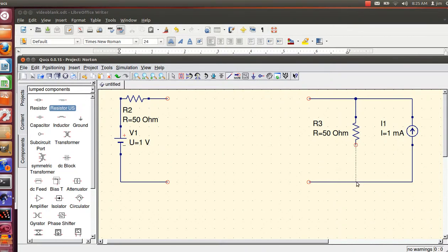Okay. So the end of the day, as a friend of mine used to say, if you do a Thevenin, you come up with a voltage source with a series resistance. You do a Norton analysis at the end of the day, you'll come up with a current source with a parallel resistance. If I was to put a black box over both of those, I could set the values up so that they would have the same characteristics. You would not know whether you were dealing with a voltage source with a series resistor or a current source with a parallel resistor. You just wouldn't know. So anything can be in the black box.